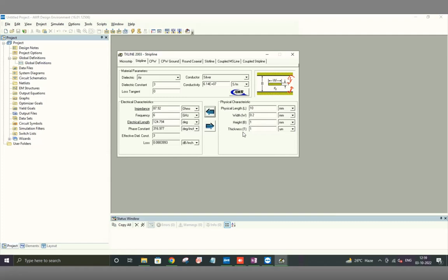You don't want the width to be too small compared to the gap, to have a more proper parallel plate kind of configuration. It gives you 87 ohms, so let us make it close to 50 ohms. So that we need quite a large change on the height, to get somewhere close to 50 ohms. This is of course for dielectric 3. So it's higher than we need.